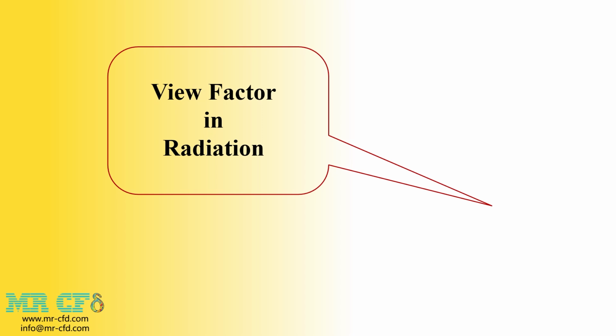Of course, we make several important assumptions to calculate the view factor. First, the radiant heat transfer happens completely uniformly on the entire surface. Second, the space between the two surfaces doesn't absorb or reflect the energy exchanged between the two surfaces. In other words, there is no intervening environment between the two surfaces.